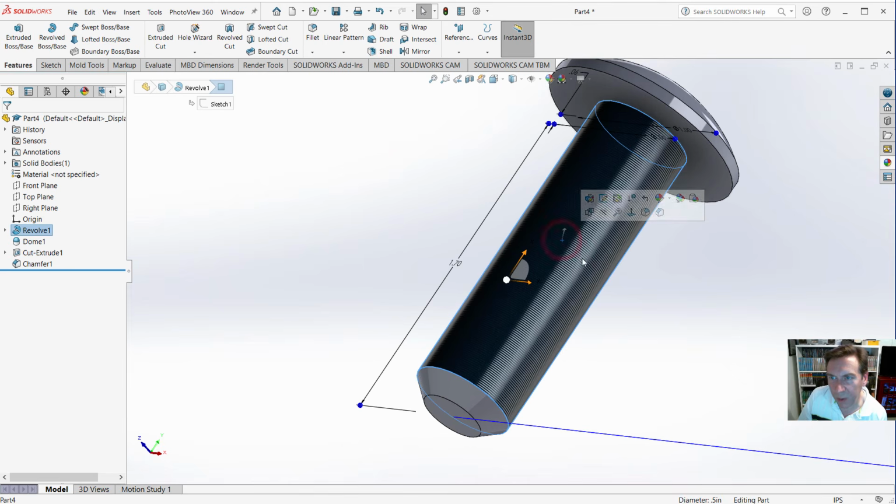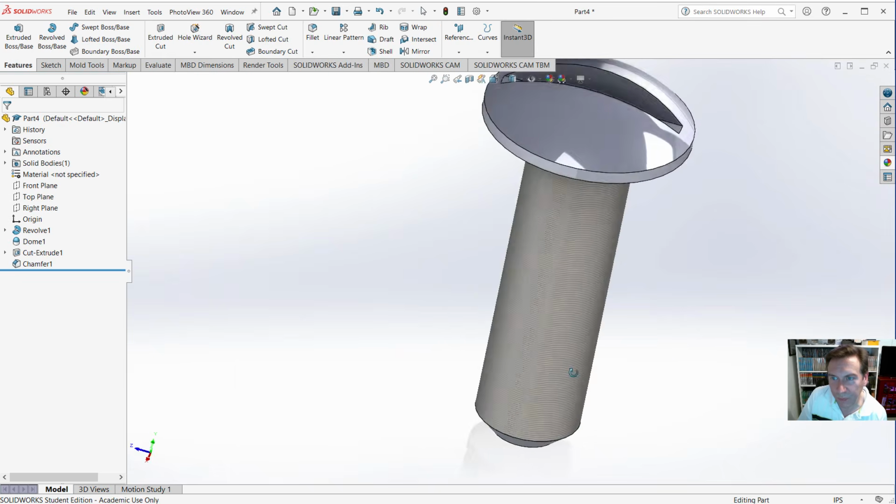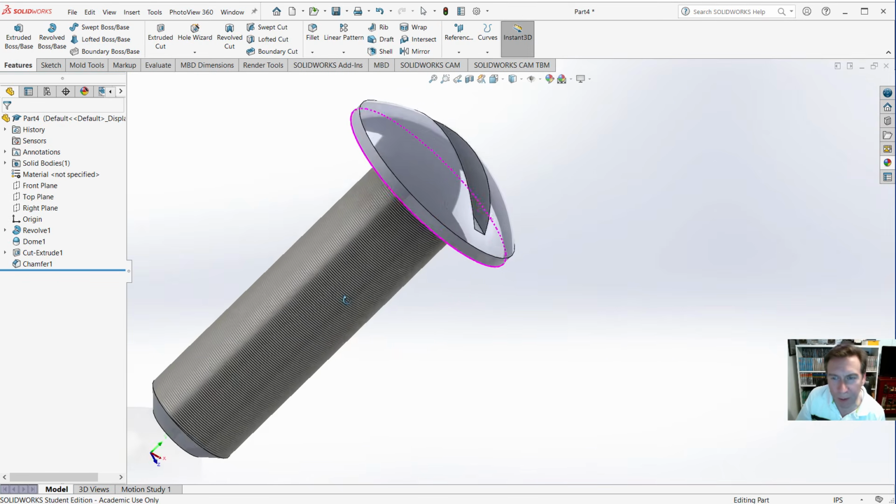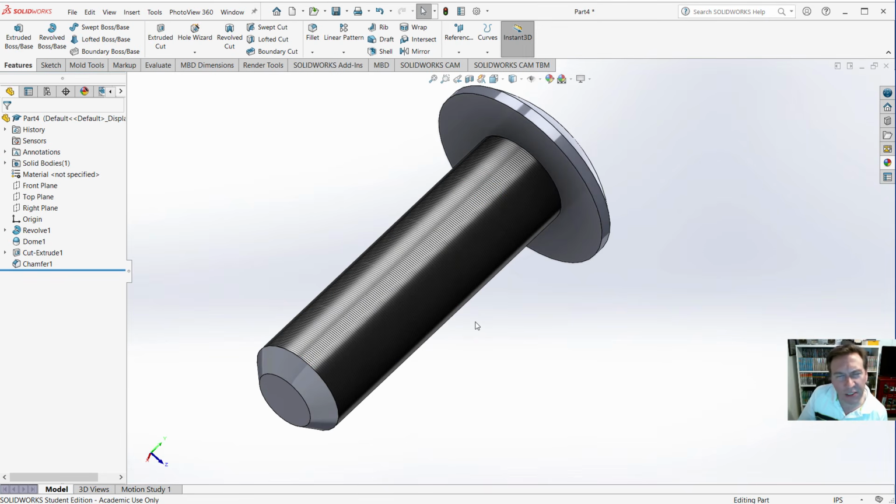And normally you could go in there and edit it. There's a little arrow that allows you to change it. You pull it, but again, my keyboard's dead. My apologies. All right, and that's just a cosmetic thread. Why cosmetic thread? Well, cosmetic threads are much more stable. They're much less intensive on the computer.